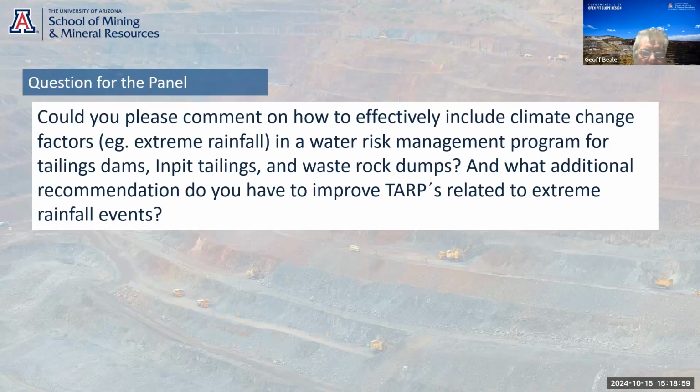The way to look at that is to understand what the failure mechanisms may be for the tailings dams or the dumps, and it's normally related to the down gradient toes of the facilities, although not always. So make sure that the implications of higher infiltration is understood in terms of what it may do for pore pressures along the critical failure surfaces.